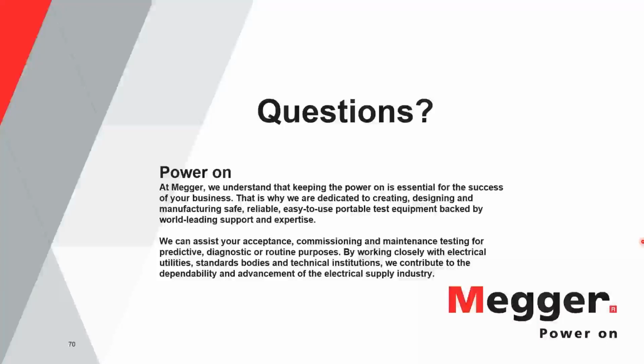Now, one of the interesting things about this is that in the IEC standard, you will see that they suggest running a zero check test. What is interesting here is that by connecting the input and the output of your SFRA on the same bushing, basically you should see a voltage output versus voltage input showing you the same voltages.